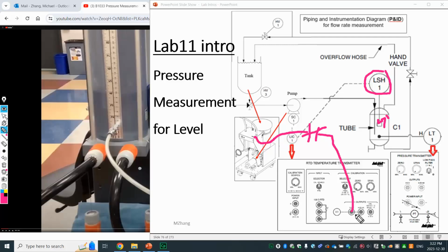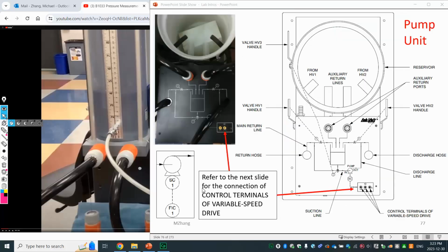So normally we can use the 5 volt and adjust around here to change the speed. Once the water level reaches the high level, this normally closed contact will become open and cut off the control power, right? The pump loses the control input, then the water level will drop, right? In this way, we protect. We don't want to have the water overflow on the reservoir, right?